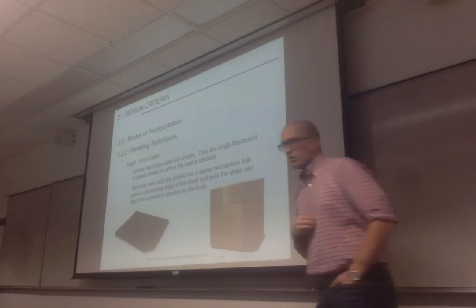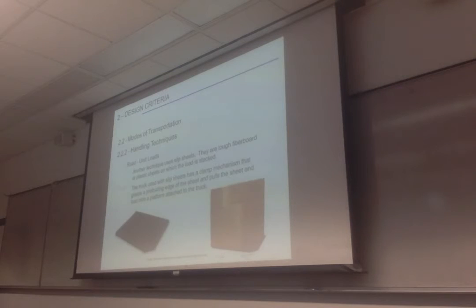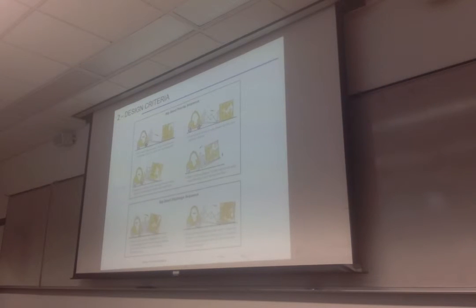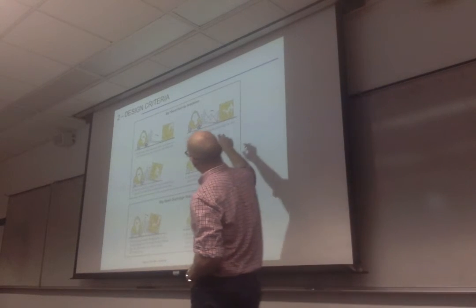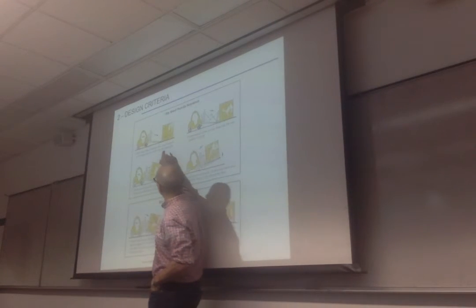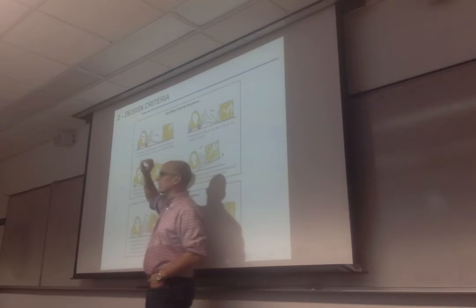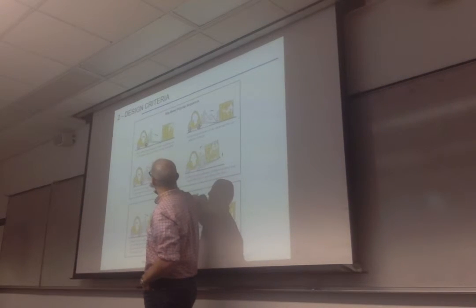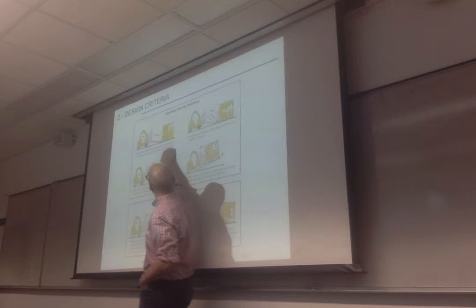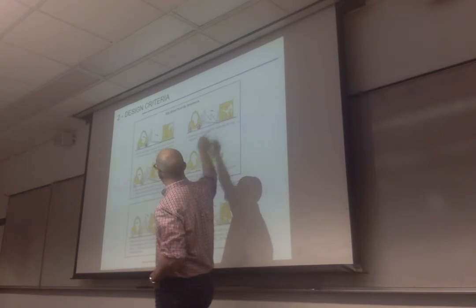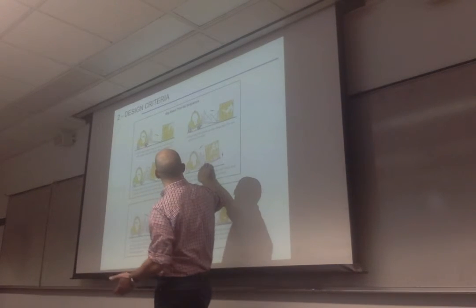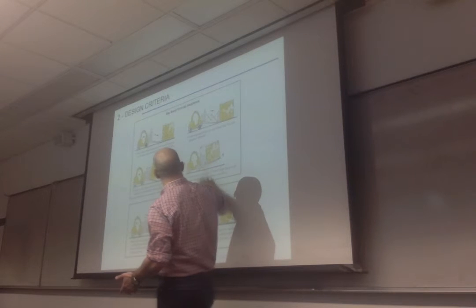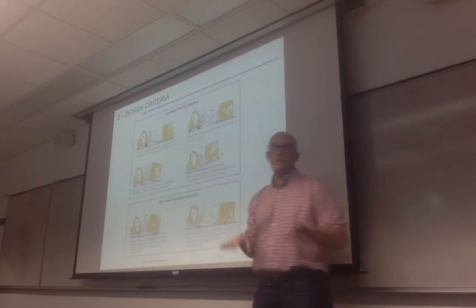So how it works is you have a special attachment on these forklifts that will come, and on these slip sheets you have a little lip that basically exceeds the load itself. So the forklift comes and grabs that lip and slides the load onto the forklift attachment, and then moves it around and slides it back and forth.